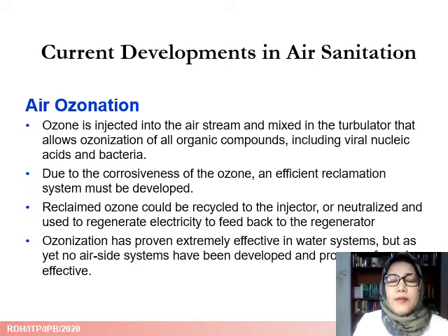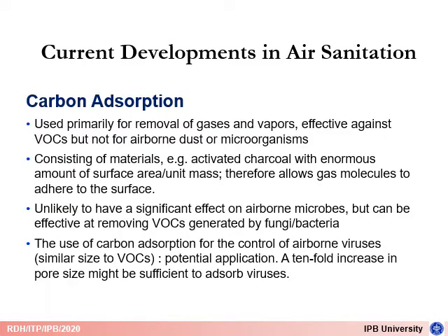Ozonization has proven extremely effective in water systems, but as yet no air-side system has been developed and proven to be effective. Lastly is carbon adsorption. This system is used primarily for removing gases and vapor and effective against VOCs, but not for airborne dust or microorganisms.